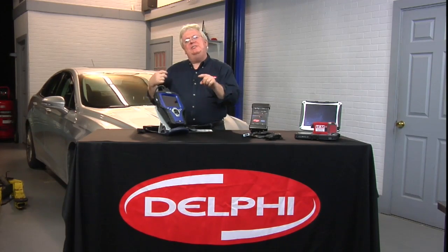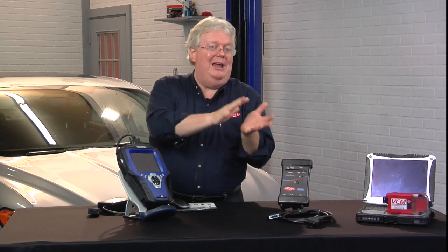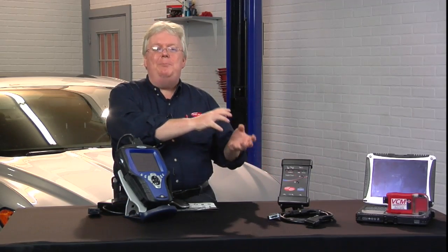However, misfires are in mode 6 in GM and Ford and others, and new Chryslers, but not older Chryslers. So depending on if misfires are in the mix of mode 6 or not, misfires are updated more continuously, and they will update mode 6 information.